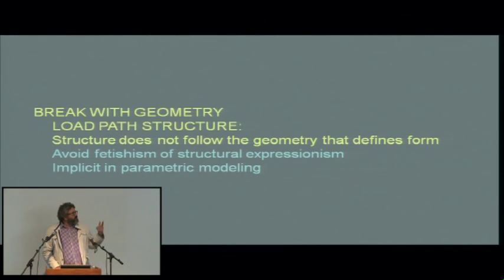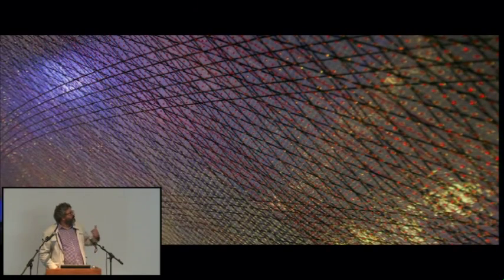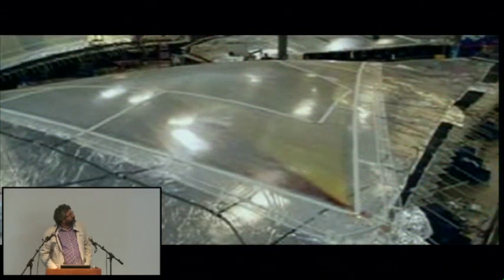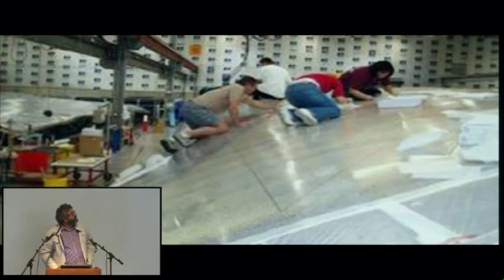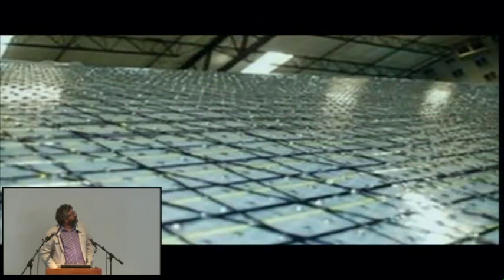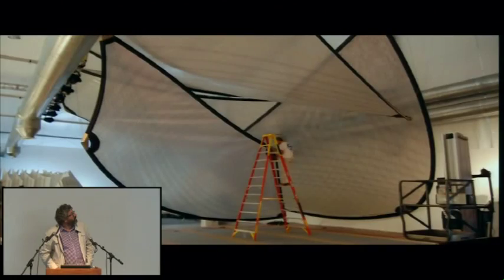And even more than a change in geometry on the surface, there are a few projects where we're starting to look at the structure in terms of load path and stress instead of in terms of the geometric frame. The first one is these hanging surfaces we did with North Sails for Swarovski, where we located carbon and aramid fibers along load paths and then sandwiched it with 30 million crystals and cooked it into these big semi-rigid shells, which you can see here.